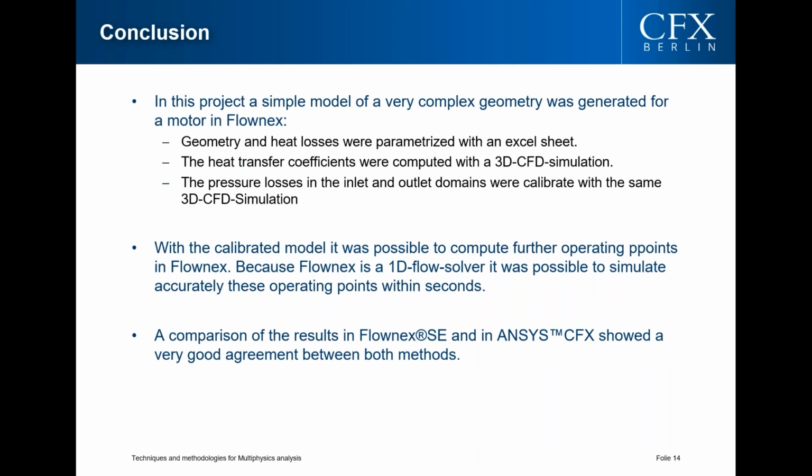And the pressure losses were also calibrated with the same 3D CFD simulation. Then in the second step, we could carry out a lot of simulations with a calibrated model, and a simulation with a 1D model lasts something like 2 or 3 seconds. And at the end, the results are essentially the same with the 3D and the 1D simulation. So it's really a big advantage for the computational engineer to use this method.